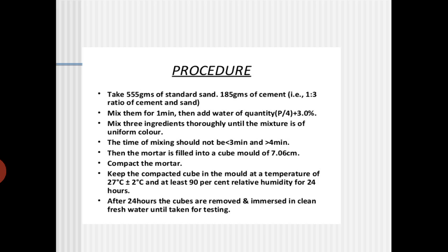Normally small pores will be there even after curing, and small mud particles will go inside the concrete and it may lose its strength during the strength test. So this is the typical process of preparation of the cubes for the cube test.